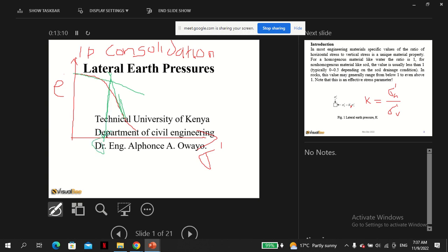So we usually call it sigma P or sigma V naught. Now this is what I was saying, that clay will remember the highest load it has ever carried in its lifetime. So if the highest load it has ever carried, sigma P, let's say for argument's sake is 100 kilonewtons, then for some reason after some time it carries a load of, say, 50,